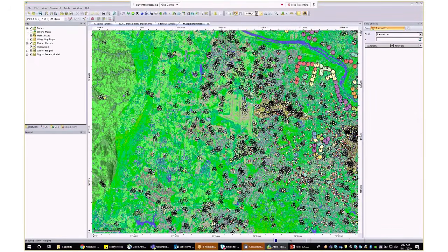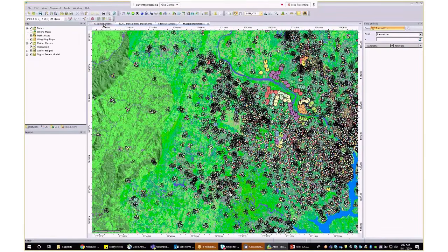See, this map window has a different zoom level, 239, and this window has a different zoom level. When we are working on a larger, complex radio planning project, we might want to view a different part of the project without losing focus on the original area. That's why we need different zoom levels, and Atoll enables us to open several map windows of the same project. This basically permits us to visually compare two separate areas of the project. So this is a very useful concept.